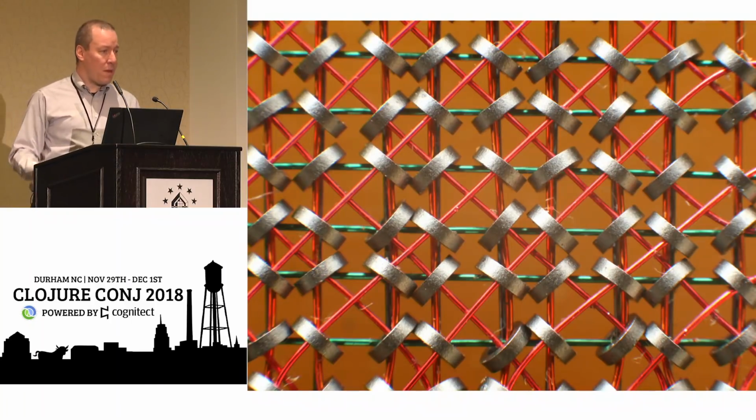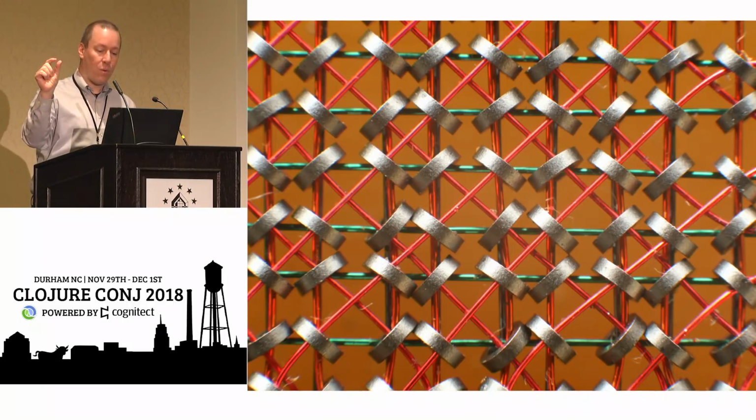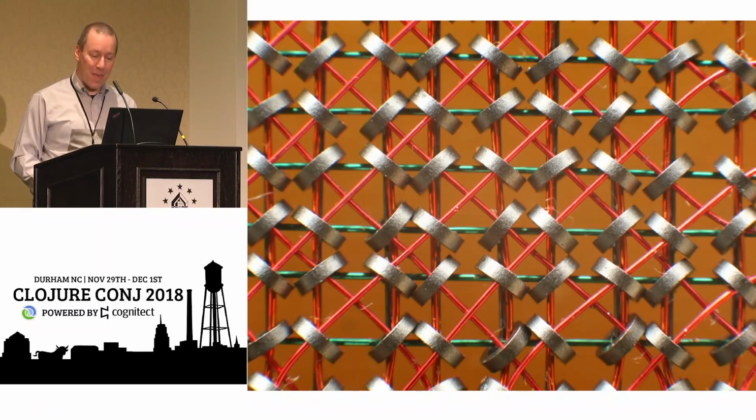This is core memory. This came along a few years later, largely replaced the Williams tubes by the mid-50s. Each of these iron toroids would hold a single bit of data magnetically, 1 bit per toroid, and you could achieve great densities of 32 kbits per cubic foot on these little iron donuts.